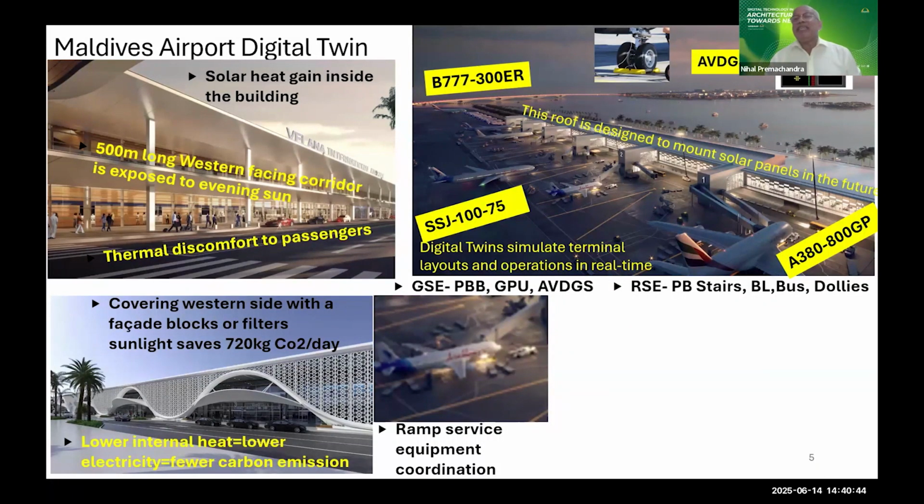And there was another clever thing that we did. We studied the temperature of the sea water. We found that 25 kilometers away from the terminal at 5-meter depth, the water has a temperature difference of 6 degrees centigrade. That difference of thermal energy is sufficient for us to run the whole cooling system. I have done the calculation with my design team, and we have proposed it. Of course, when they have money to implement that, I'm sure that they will implement it.